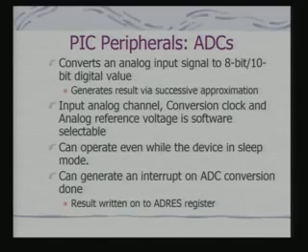Now, the reason for providing ADCs is interfacing with external analog inputs. Many of your external sensory inputs would be analog. Once we get the analog input, we convert it into digital form for doing any further processing.